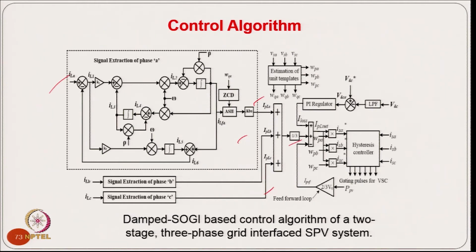So that gives a kind of averaging or load balancing. Then we have a reference DC link voltage, and a PI controller which represents the loss here. We are getting a feed forward term from PV power, which is also represented in terms of the current amplitude on the grid side. This is the net current we are supposed to have in the grid after the losses and after feeding the load locally, and we have a phase.